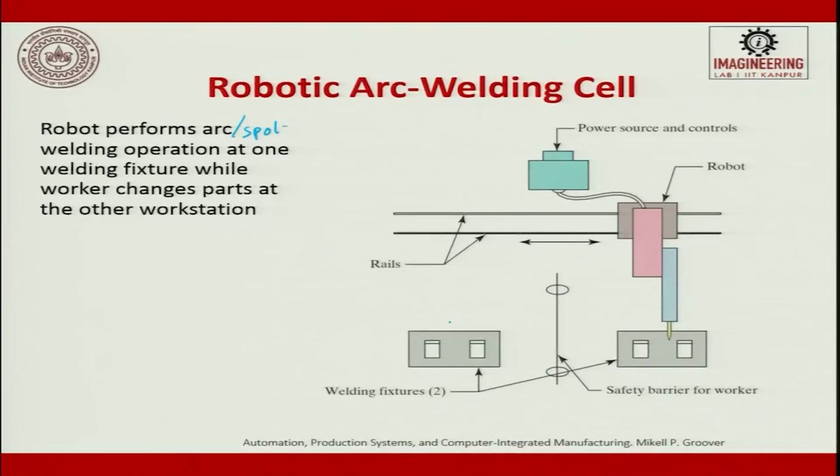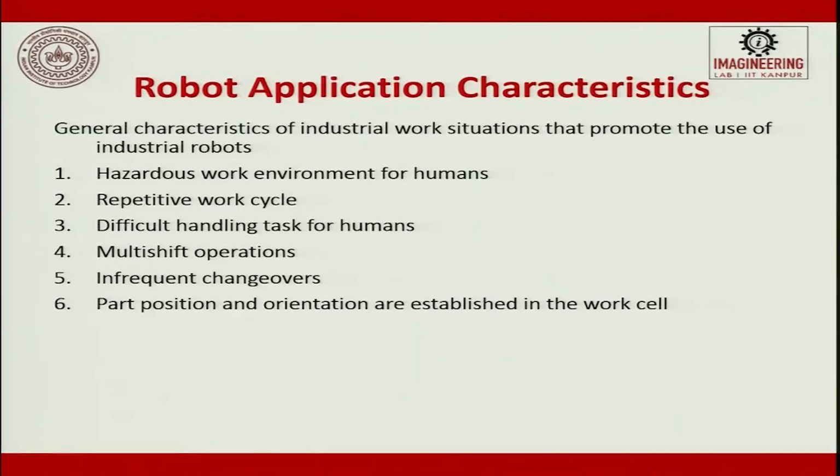So, the moment it is ready, this swaps, this goes inside and this fellow comes outside, and the arc welding process continues. Here it can be in a straight line, it can be in a contour, you can have multiple axes either to the robo arm or to the workpiece to make complicated welding joints easy. The moment you say arc welding, you can fix a laser, you can fix a water jet to get complicated profiles. Today we have 5-axis water jet cutting machines, 5-axis laser welding machines.